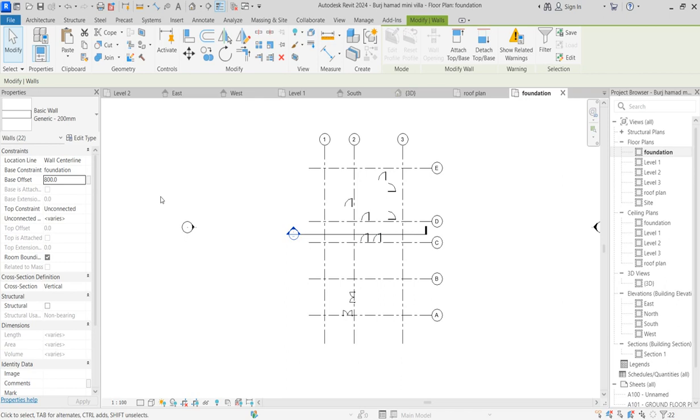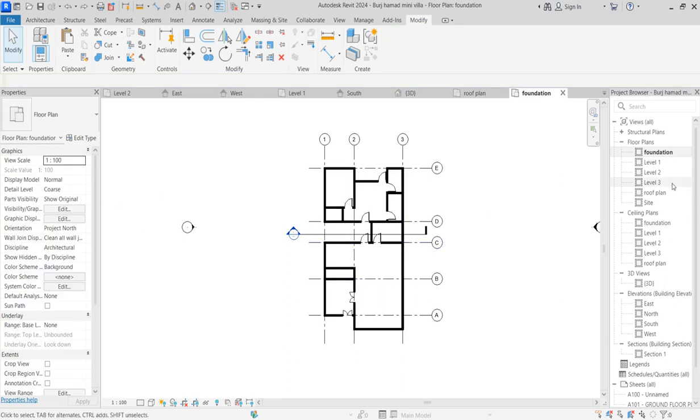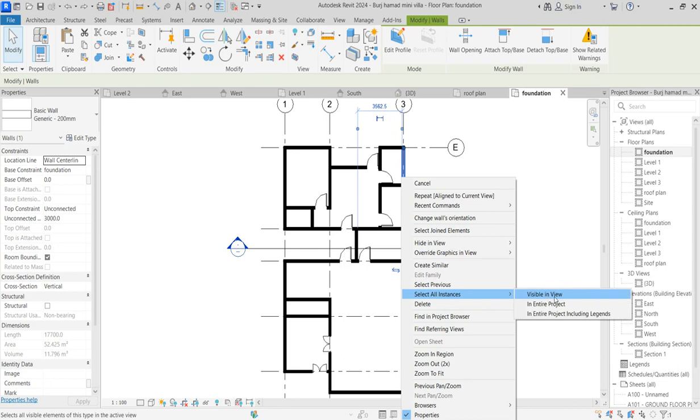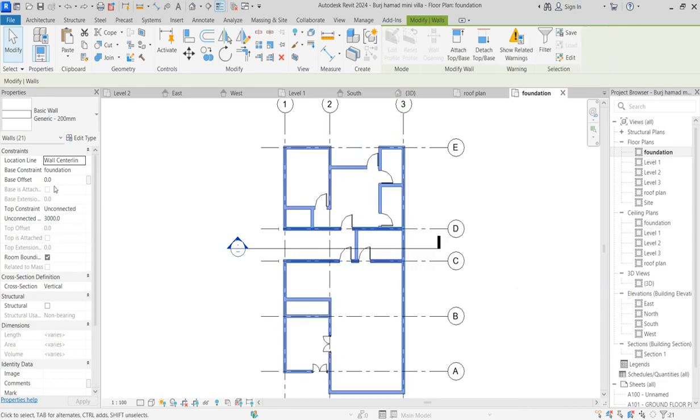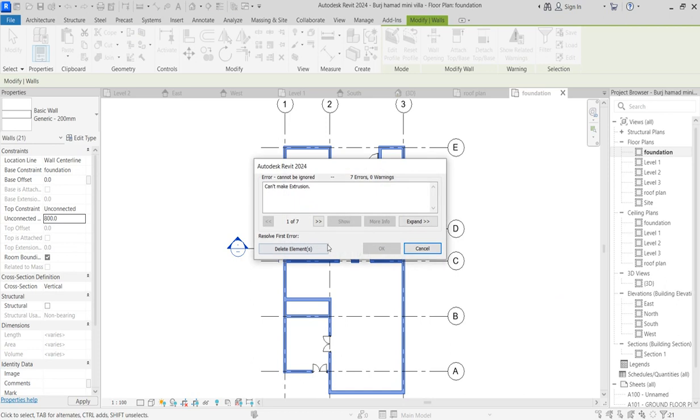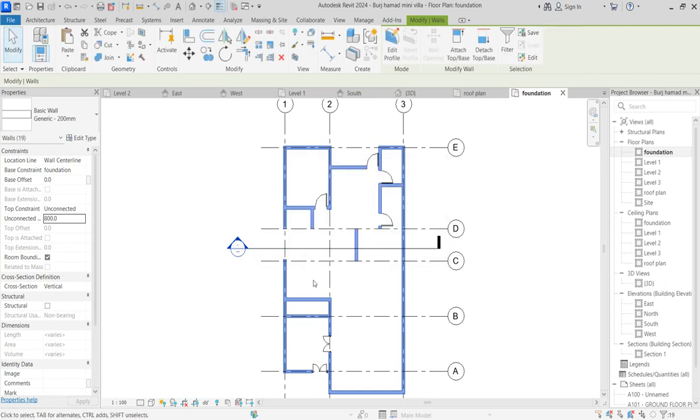Something is missing. Base, no, not base. Click it, Ctrl 0. So go back to select all these instances in this level. Select everything. From here, this is where we do the base. We just go to change the connected height to 800. So finish. You delete all the elements, everything that is not reasonable.